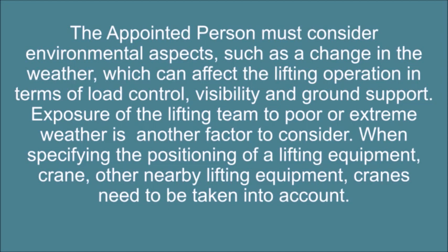The appointed person must consider environmental aspects, such as a change in the weather, which can affect the lifting operation in terms of load control, visibility, and ground support. Exposure of the lifting team to poor or extreme weather is another factor to consider.